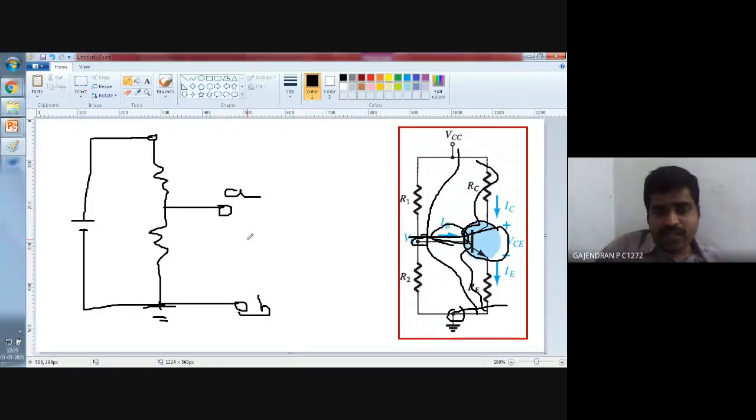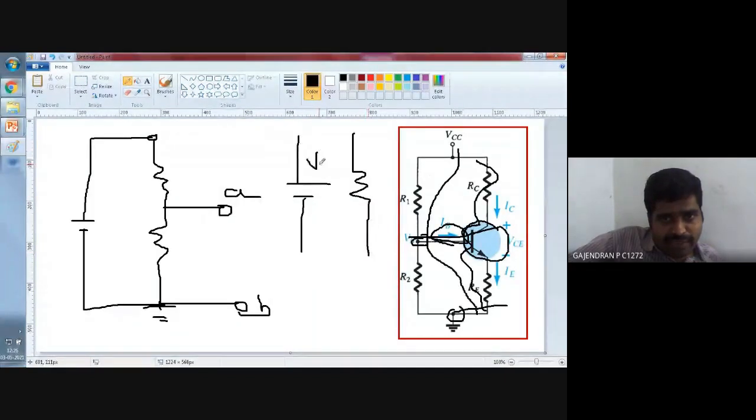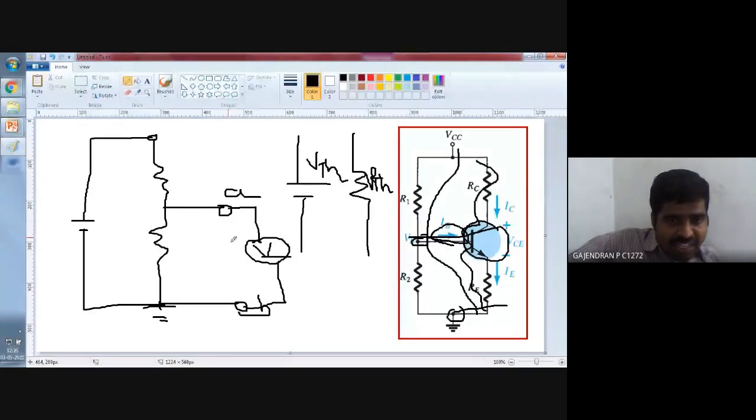Okay? So in Thevenin's work, you need one voltage and one resistance value. This voltage we are going to name the Thevenin voltage. This we are going to name the Thevenin resistance. I will tell you one thing. The Thevenin voltage is very simple. If I connect one voltmeter across this, whatever voltage appears in this open terminal is your Thevenin voltage.